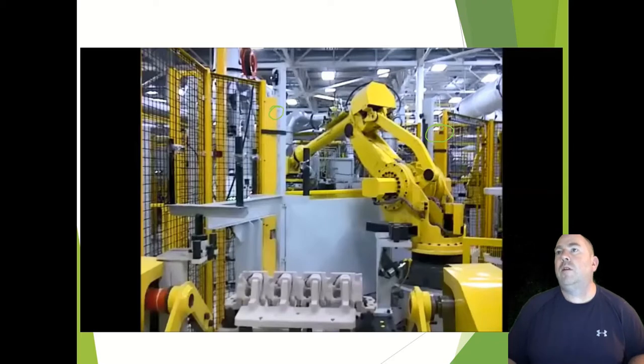These are door limit switches, so that detects if this door is all the way up or not, because when it's all the way up, we have our perimeter guarding okay. So we want to be able to have a safety device that detects the position of that door. So that is a safety gate switch right there.